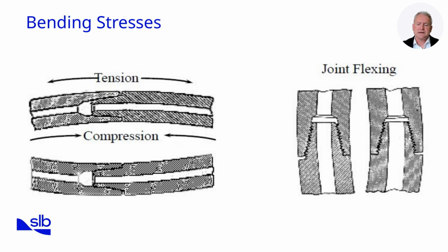The level of bending stress is directly linked to the degree of curvature. A gentle bend spreads the stress over a longer section, while sharp doglegs concentrate it in a much smaller region. This explains why even minor changes in wellbore trajectory, if abrupt, can significantly weaken the drill string over time.